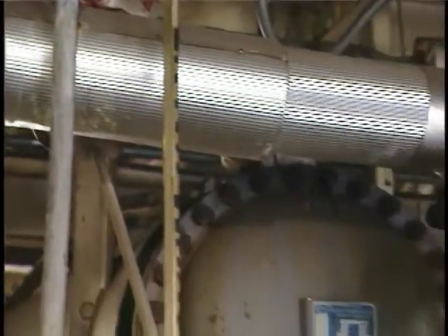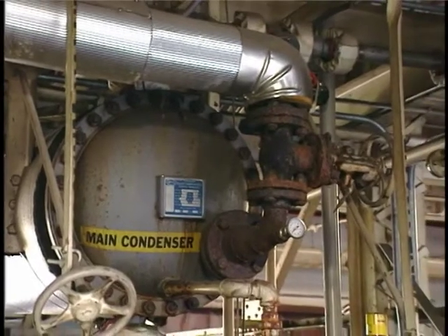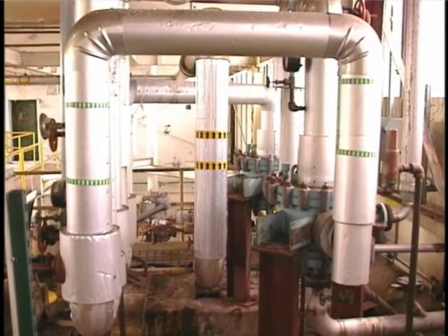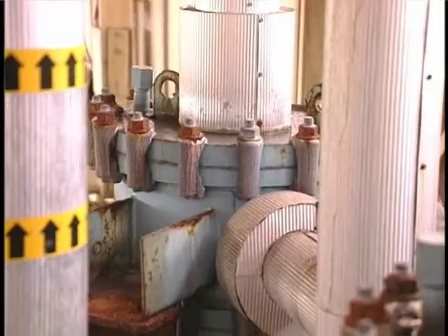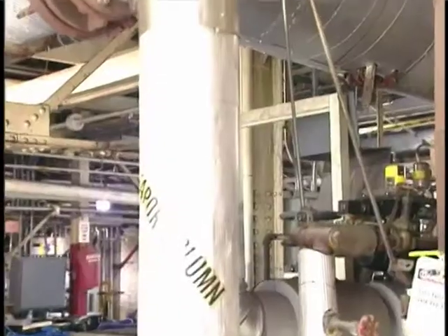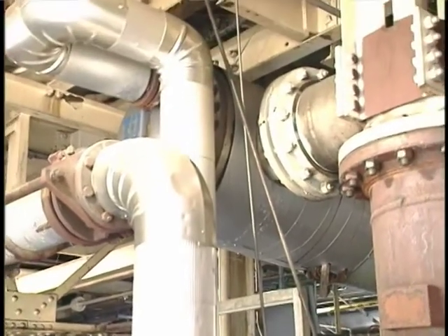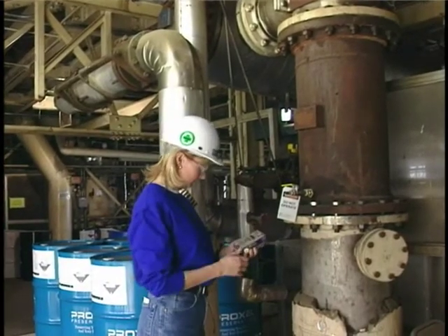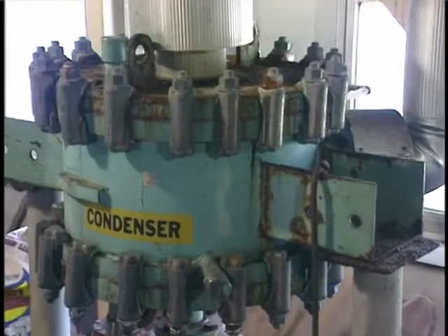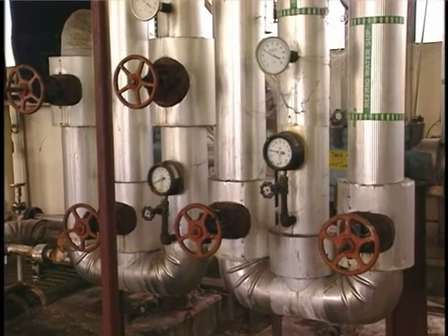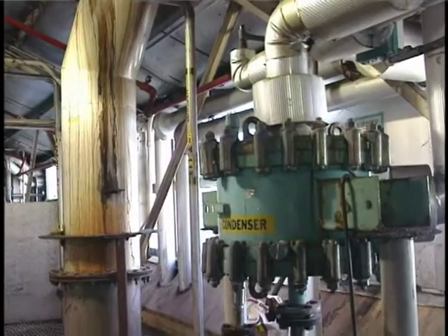The coolant flow rate and the coolant inlet and outlet temperatures can be used as direct indicators of the condenser system performance. Reductions in the coolant flow rate or reductions in the temperature difference across the condenser indicate reduced heat transfer, reducing the collection efficiency. Decreased gas flow rates will result in reduced capture of the contaminants at the source, resulting in fugitive emissions. Low gas flow rates may result from the buildup of ice or frozen organic compounds in the condenser. Decreased fan motor currents and decreased hood static pressure indicate a decrease in the gas flow rate.